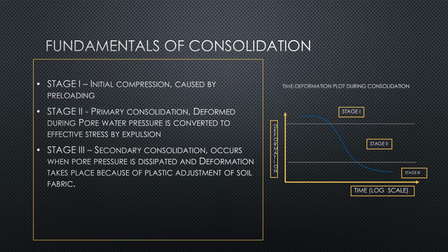At the end of stage 2, the primary consolidation, the deformation slows down gradually, because at the end of primary consolidation, the water is completely expelled. That will be the end of the primary consolidation.